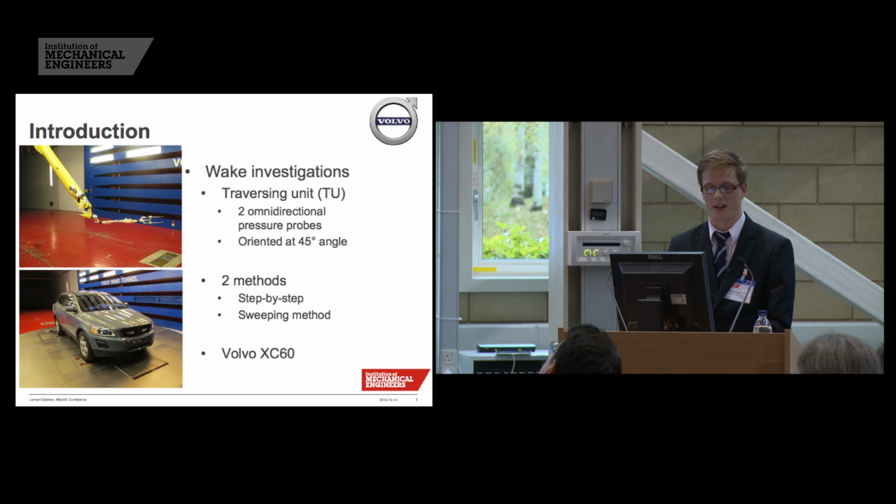We have a step-by-step method where we go from point to point, and stay there for 2-3 seconds, over which the pressures are averaged, and then we move to the next point. The second, newer method is a sweeping method where we sweep along one axis before going to the other axis and going backwards. Then we use a filtering technique to get the average pressures out of it.